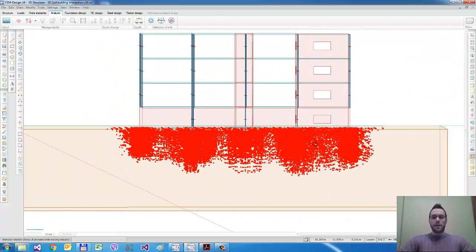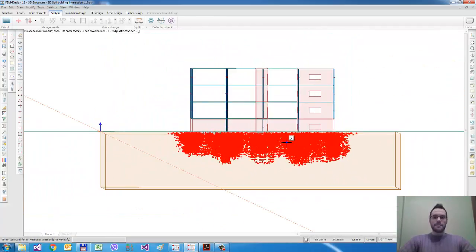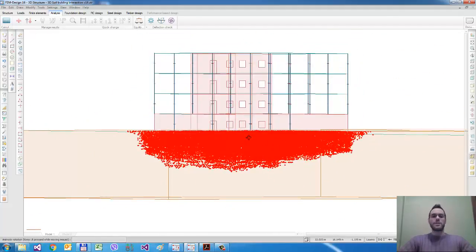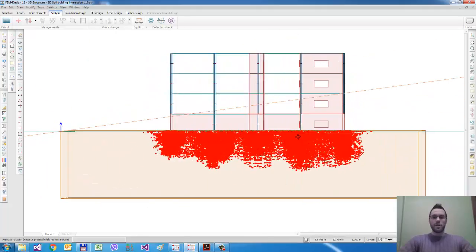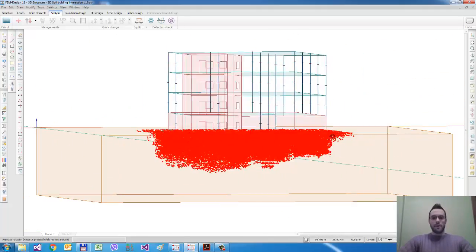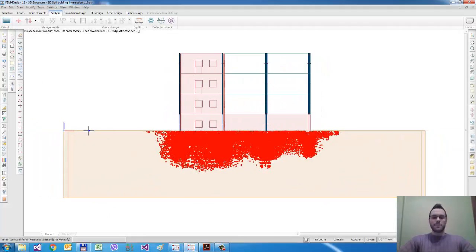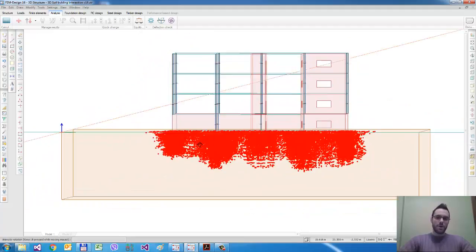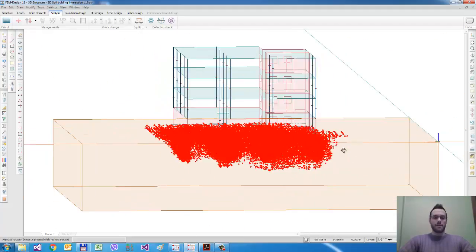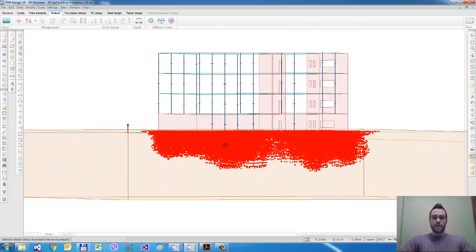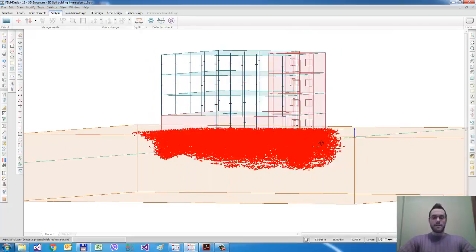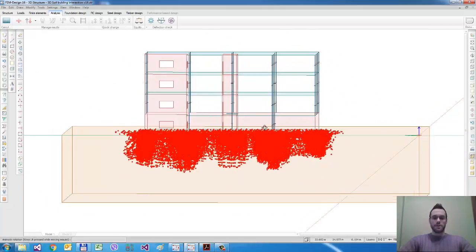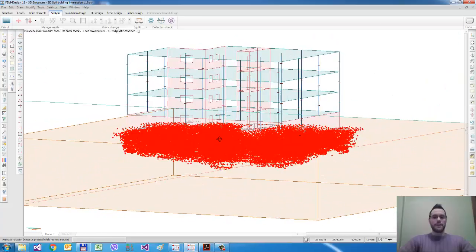But it doesn't mean that the soil loses its stability or that we reach the load bearing capacity of the foundation, because there is no compound slip surface around the building. Those points are in plastic condition. We have plastic deformation under those foundations. That's why we get larger settlements if we consider the nonlinear behavior of the soil in the settlement calculation.